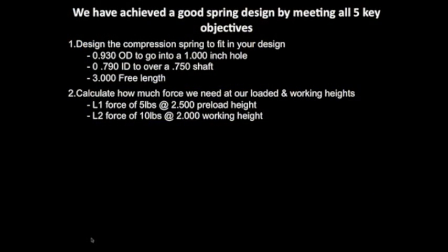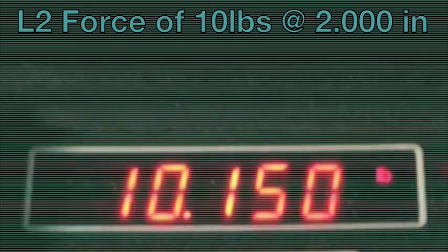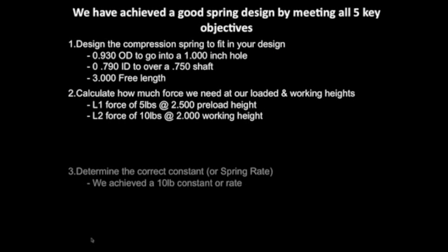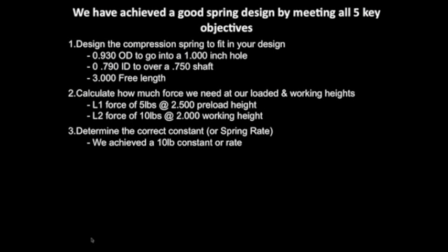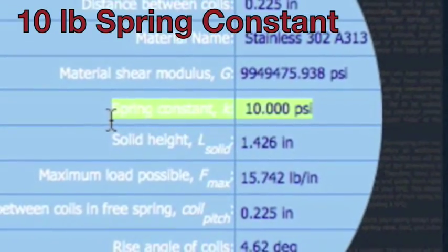We calculated how much force we need at our loaded and working heights. L1 force of 5 pounds at 2.5 inch preloaded height, L2 force of 10 pounds at 2 inch working height. We determined the correct spring constant or spring rate. We achieved a 10-pound spring constant.